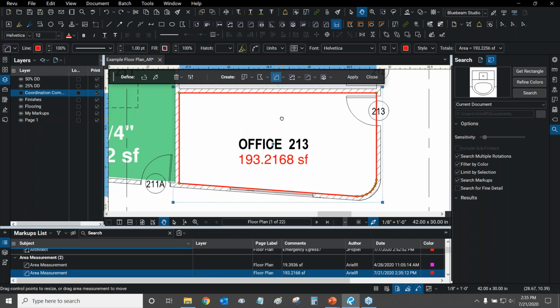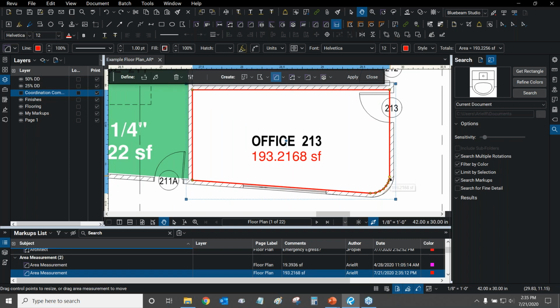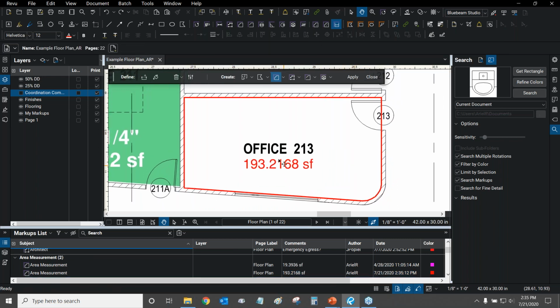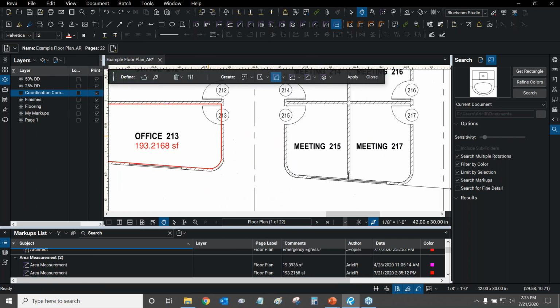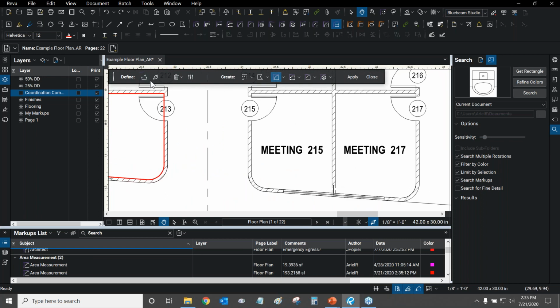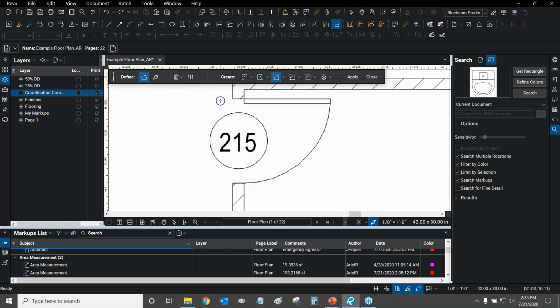And this is how we can use dynamic fill to calculate this really difficult rounded corner and lines that are not perfectly straight on the cardinal directions. So this one, for example, this wall is slanted a bit. So dynamic fill can help us calculate it very quickly. If I did it without explaining it to you guys, I would basically do it very quick. I'm actually going to show you how quick dynamic fill could be used.